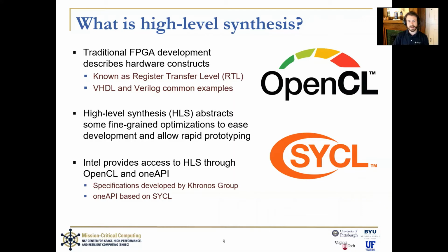High-level synthesis, on the other hand, abstracts some fine-grained optimizations to ease development and allow rapid prototyping. Often in the form of C or a C++ compliant language, this allows FPGA developers to describe logically or functionally what the accelerator should do, rather than describing the hardware under the hood. Intel provides access to HLS through OpenCL and oneAPI, both of which are specifications developed from the Khronos group. oneAPI obviously is based on top of SYCL and provides additional extensions.